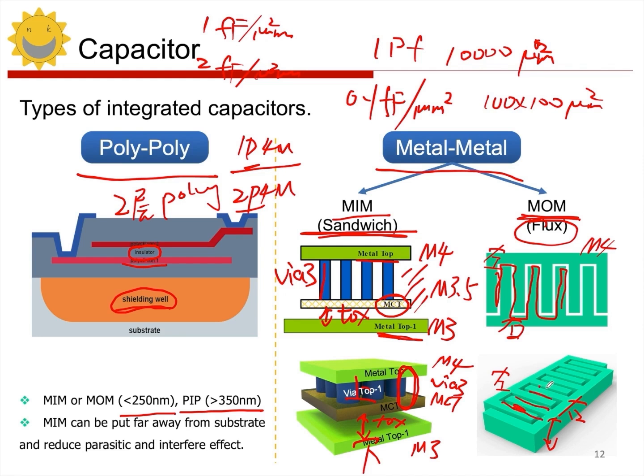These sidewalls here and there all have integrated capacitors present. So these capacitors make up the capacitor device, right? So you see this capacitor, right? So what affects the unit capacitance? Is it the distance between the two electrodes? If the distance is very close, the density will increase. Otherwise, the density will be low. So by adjusting the density, and by adjusting the size of the capacitor, what can be controlled? The number of fingers and their length, right? Both can be used to control the size of the capacitance. Note that this is the structure of the MOM capacitor.